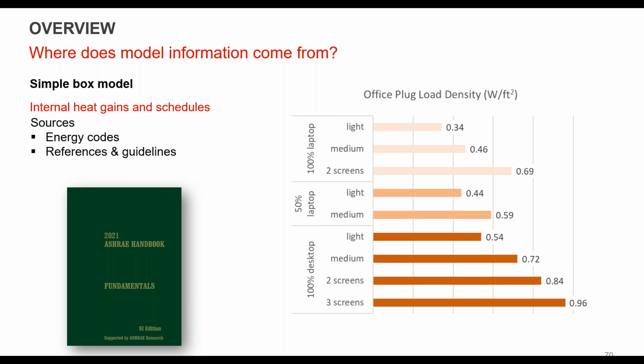Sam, there's a question about lighting power. Yep. The old building information we will talk a lot more about, but for lighting power, the question is whether lighting power goes into heat gain. It depends on the type of lighting. If you have a recessed LED fixture today, where your driver is up above the ceiling in a typical office install, you're probably only getting 20% of that heat into the space off the front side of your LEDs. That's basically just conducting through your fixture.